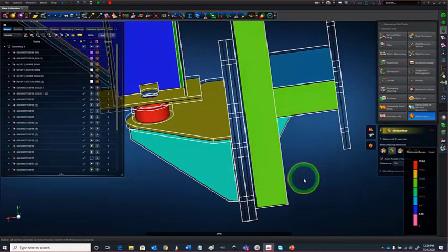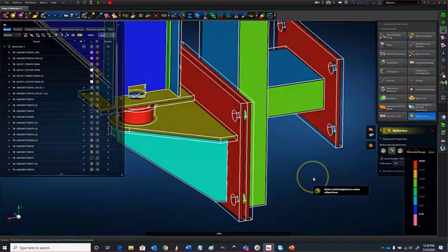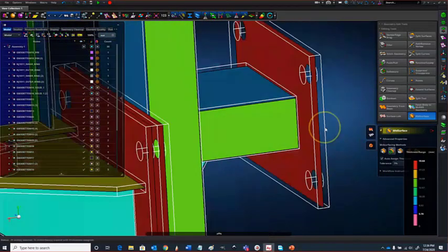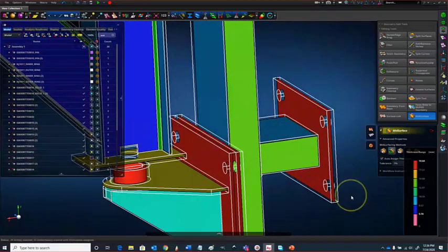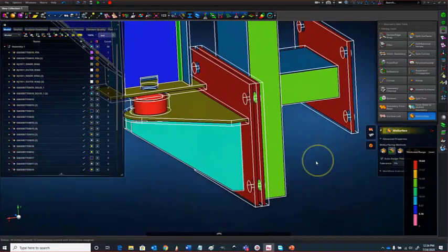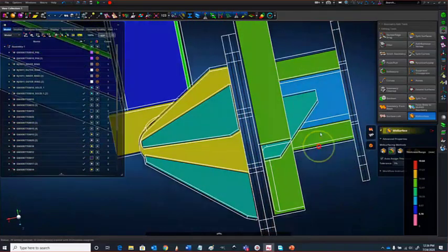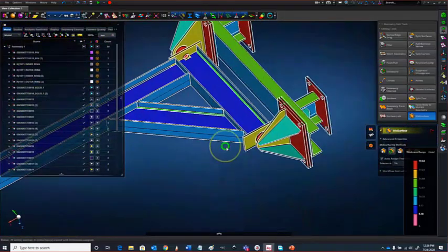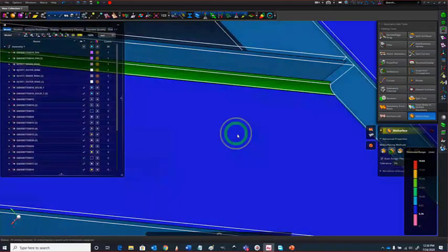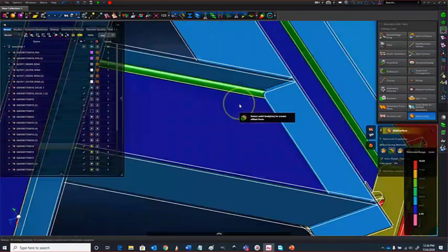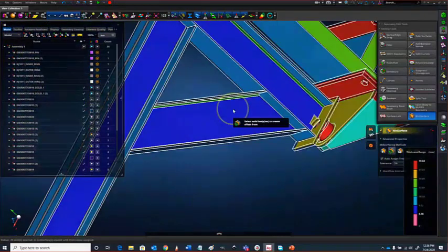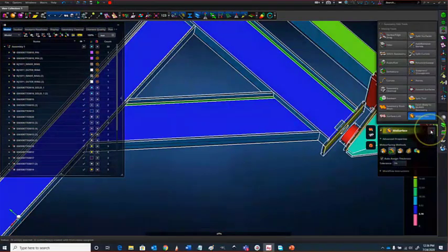So for instance, in this case, we see that the majority of mid surfaces were created quite nicely with the appropriate thickness assigned. The only exception being these beam sections over here, because the large fillets changed the outcome of the mid surface, unlike how we would want it.